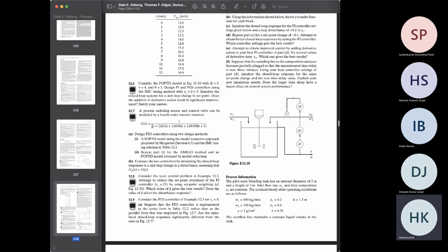You will have to appropriately simplify this model into second order. You can approach the Skogestad method or Taylor series, whatever is given to you, then come to either first order or second order. This is another thing that you have learned previously, which would become handy.